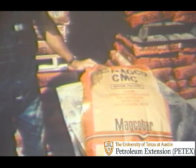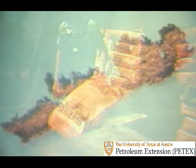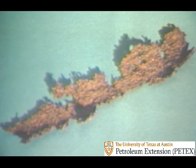Chrome lignosulfonate, called Spersene by this company, is a good chemical for reducing the viscosity of a saltwater mud. Corrosion may be a problem when using saltwater muds. You know what saltwater does to steel that is exposed to air. You can avoid this by adding an oxygen scavenger to the mud.